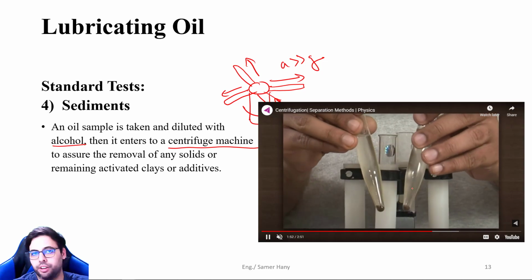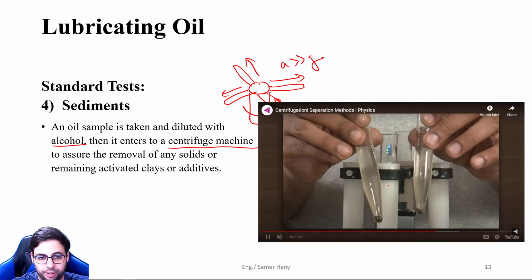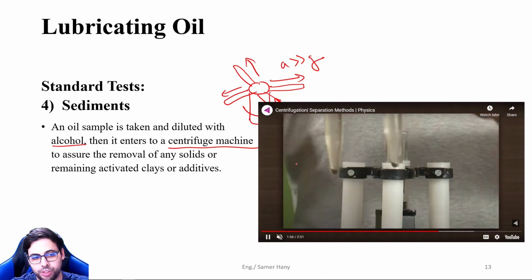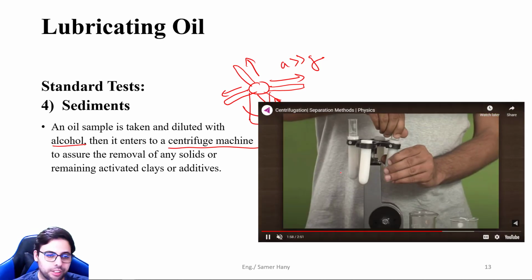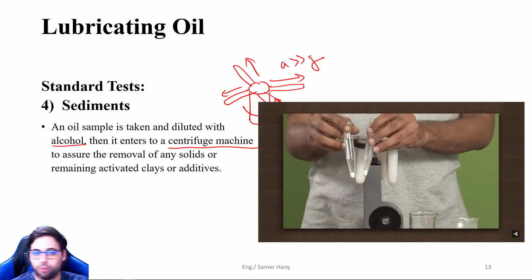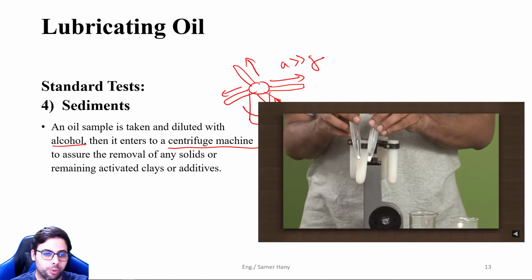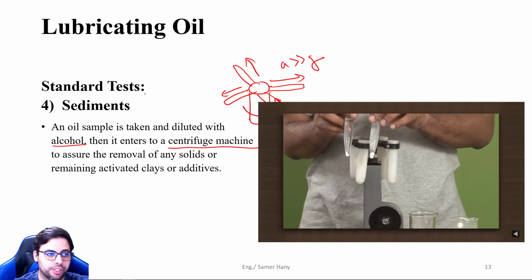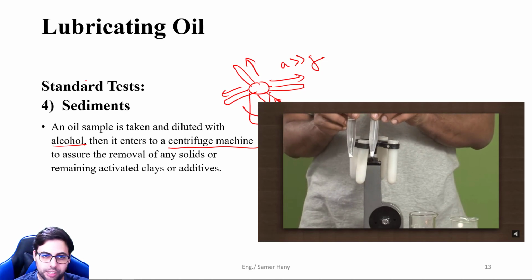As you can see, the solids settled down at the bottom of the test tubes. This water is not yet 100% clear, but if you wait for one more minute, it will be. So that's how we measure the sediments in our oil sample.